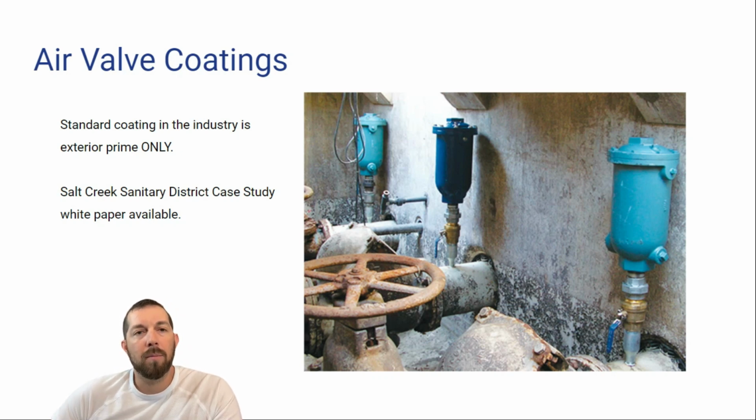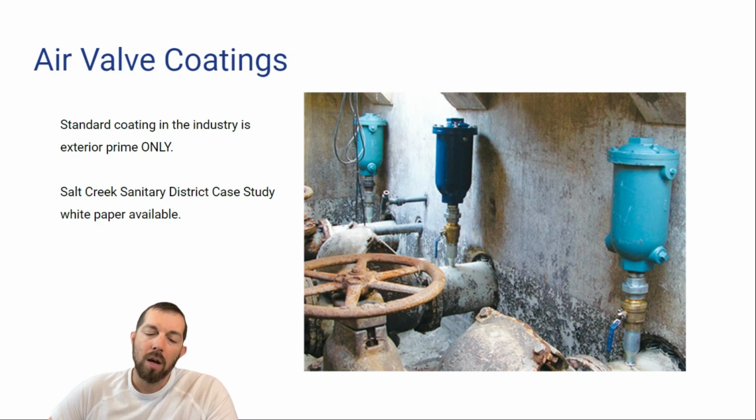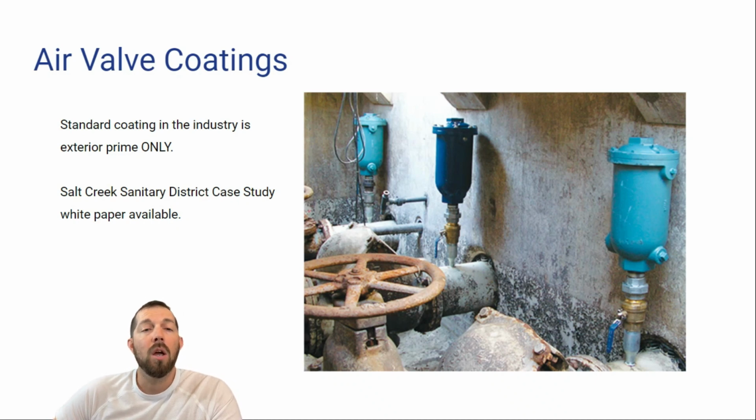When we're talking about iron body valves, something to consider. We want to obviously keep the rust down. Most manufacturers also have standardized on 316 stainless steel internals to minimize any corrosion issues long term as well. But when we're talking about coatings of the valves, again, exterior prime only is the standard in the industry. There's also 2-part epoxy that's an offering, and then also there is fusion bond epoxy coating, which is also another offering.